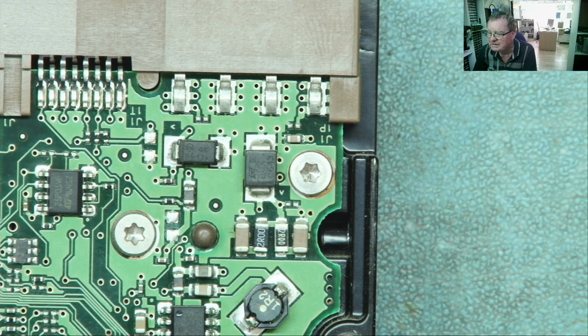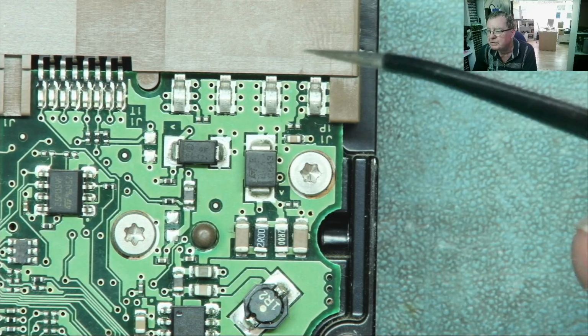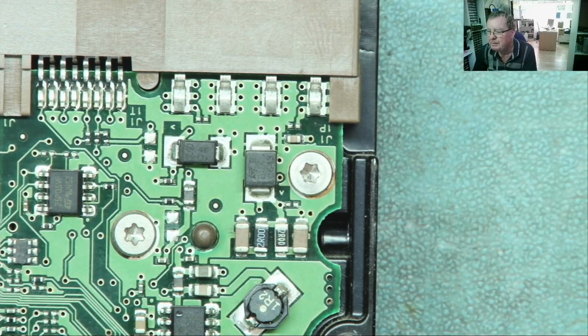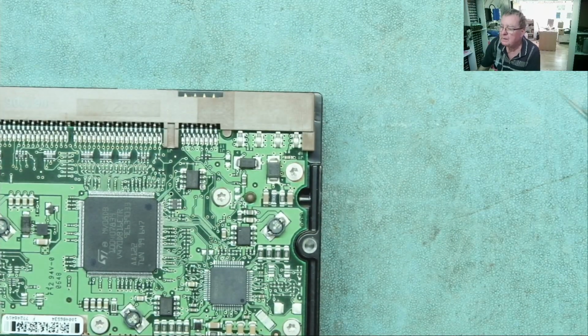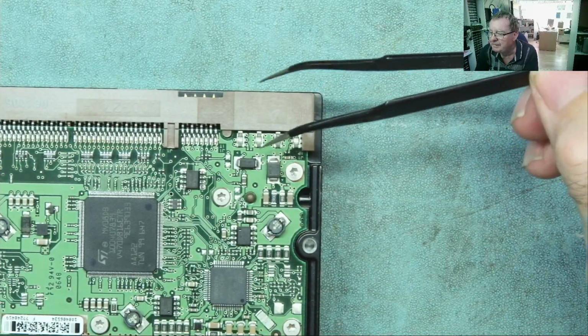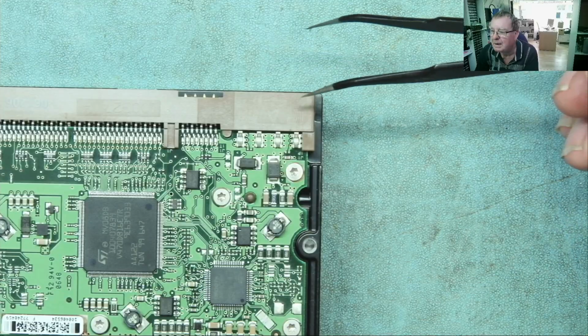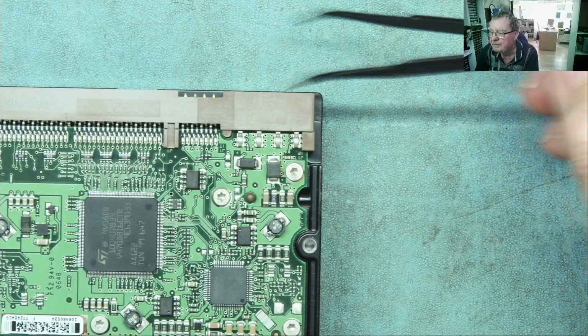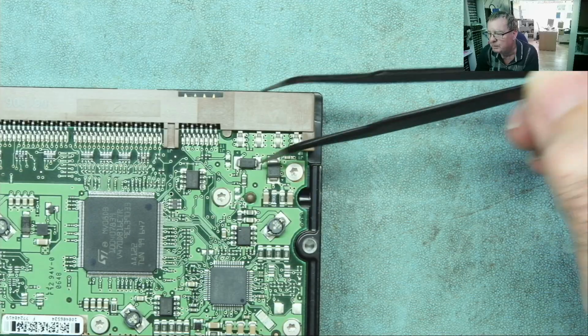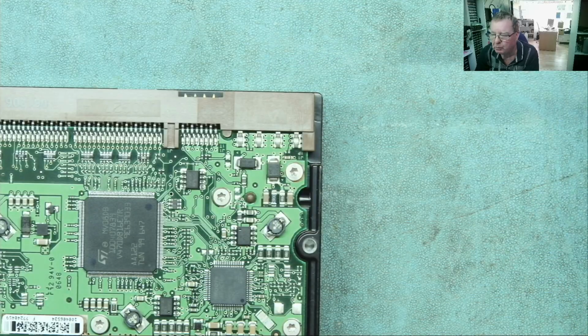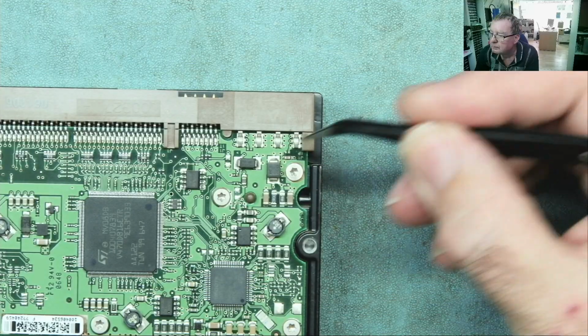So a TVS diode is basically the same thing really as a MOV, but it works on a much lower voltage and it's connected across the voltage input. This is a hard drive. You may well find a TVS connected from the 5 volts to ground, and the idea is that if you accidentally put 12 volts into the 5 volts due to an incorrect cable, this thing will go short, and they do go short. So TVS diodes go short.